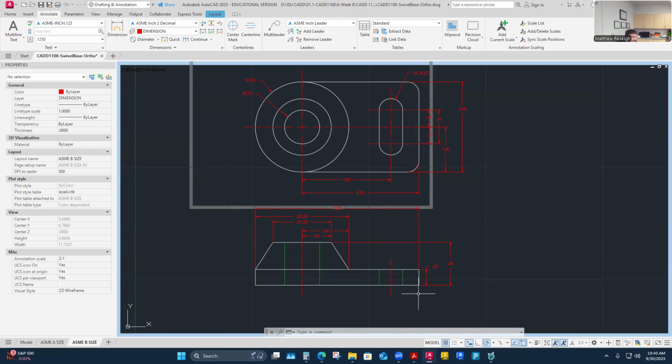And here, I've got the base pulling up my heights. So that's a control point in my front view. And then I've established this one, which is the same as this one. So really I've established 2, and my third one is this way. So I've got 3 controlled points where I'm pulling all my dimensions from. And if in the future I establish those as what we call datums, then those things are easy to evaluate apart from those 3 datums.